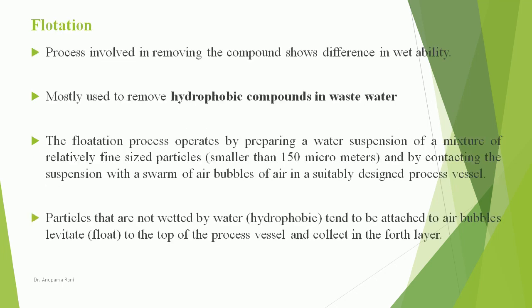Next process is flotation. The process involved in removing the compound shows difference in wettability. Mostly used to remove hydrophobic compounds in wastewater, the flotation process operates by preparing a water suspension of a mixture of relatively fine-sized particles smaller than 150 micrometers and by contacting the suspension with a swarm of air bubbles in a suitably designed process vessel.